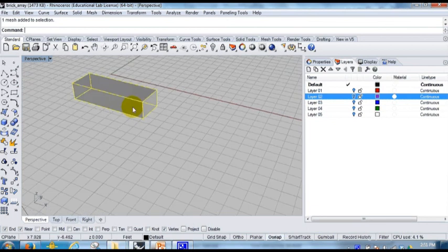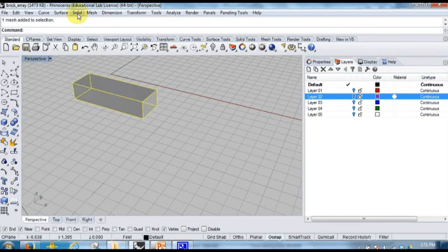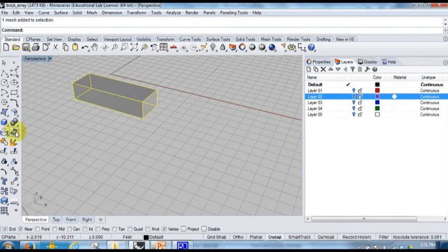Simple like that. This brick, I made this by a mesh. So if I make a selection, you can see Rhino will tell me this is a mesh rather than a polygon, rather than a surface. This might be the technique you already know. In Rhino, when you create geometries, you can either create as a solid, it's basically a multiple surface, or you can create a mesh. So if I do a box, there's not much difference, except the mesh is easier to compute. So here, if I create a mesh, I can actually do it here.